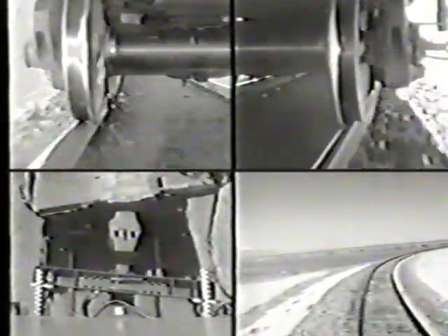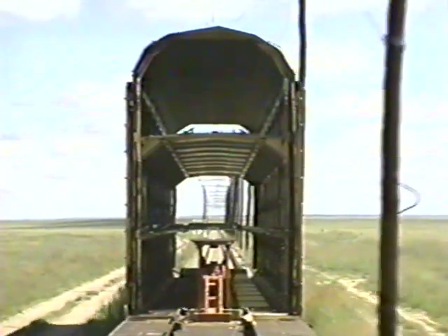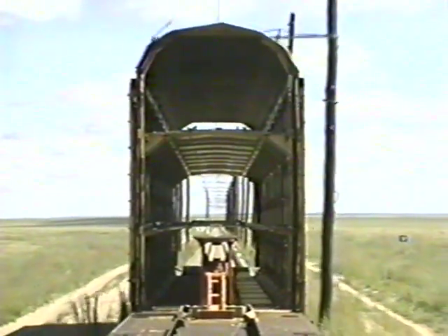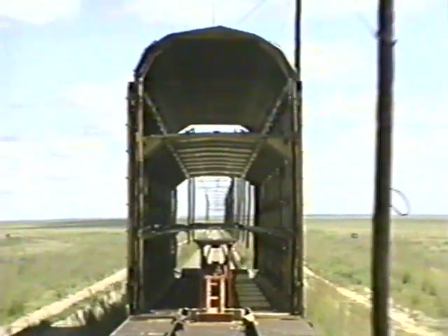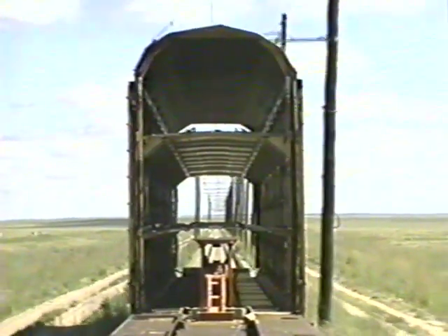The dynamic flange climb derailment scenario is similar to the low-speed flange climb derailment scenario, except that the increase in lateral forces and wheel unloading are also affected by higher train speeds. Such potential derailments may result from rail car hunting at high speeds. Rail car hunting refers to the unstable lateral vibration of the rail car trucks at higher speeds.